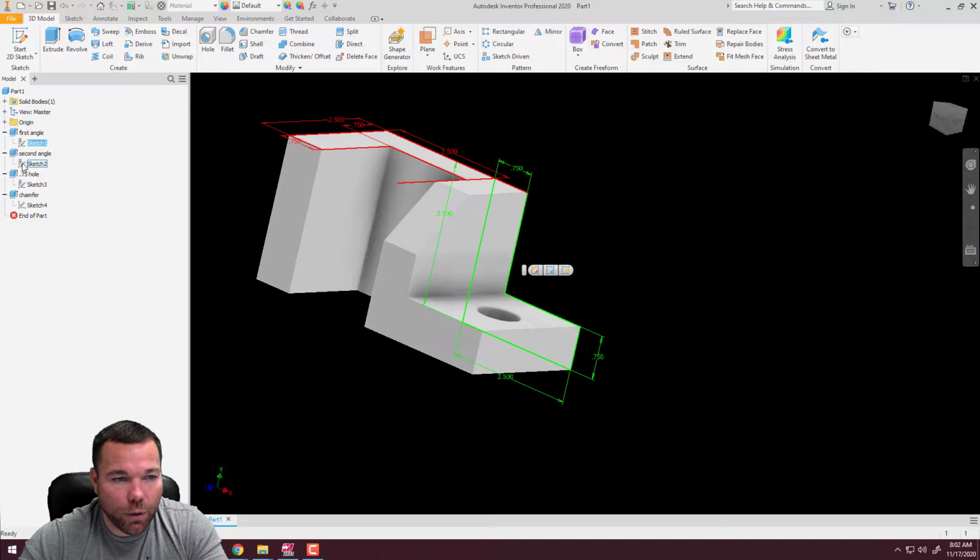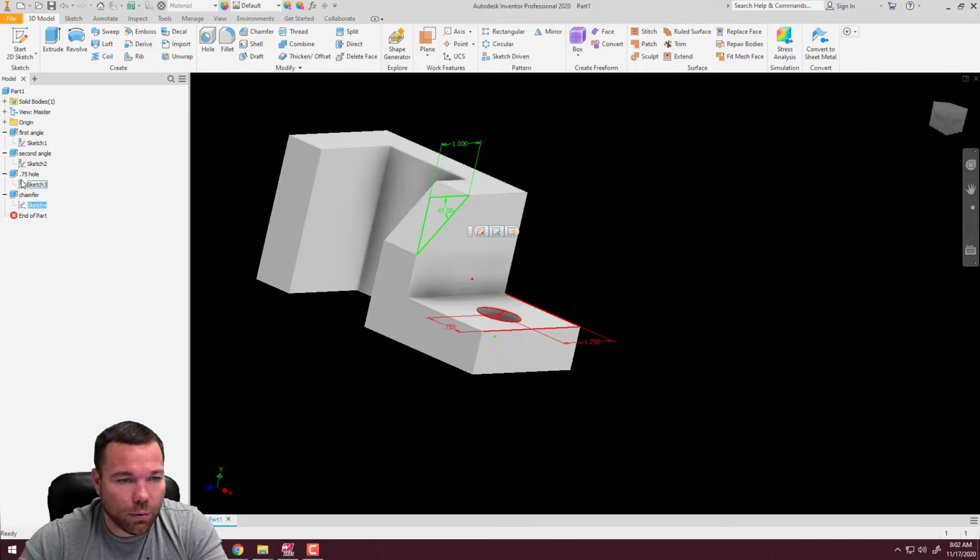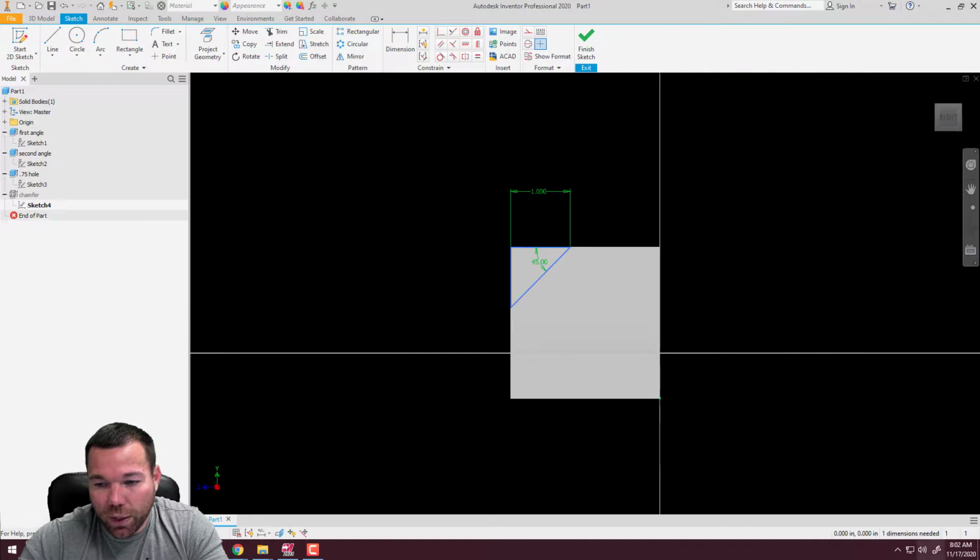So if you hover over these, you actually have to have your mouse over top of this little drawing thing. I was trying to hover over here. I was wondering why it wasn't coming up. It'll actually tell you if it's fully constrained. Okay, so here you can see it didn't come up. So that one's suspect.